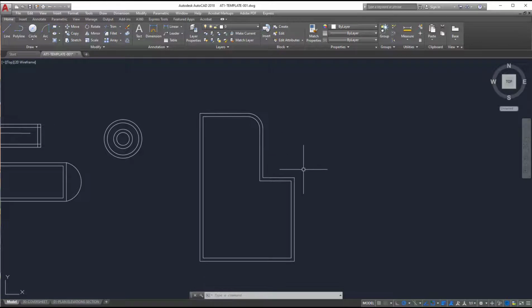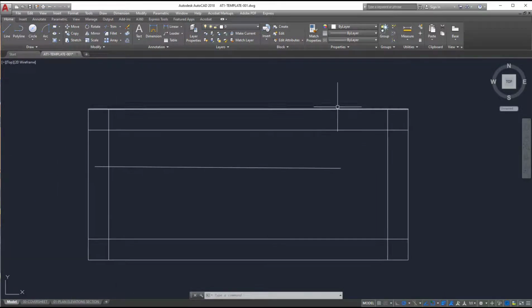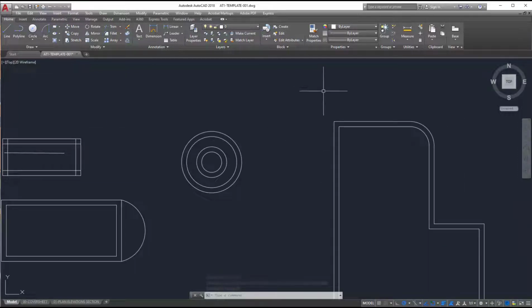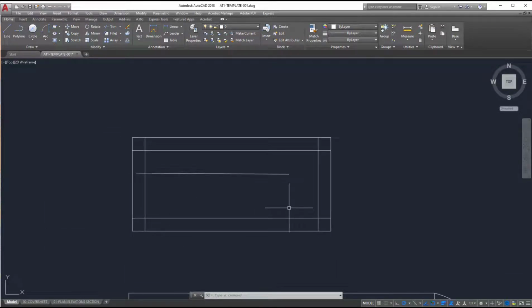The next one is trim. So trim is a great tool. And let's go back to this rectangle to use the trim command. So we have these outside walls, and we have these inside lines that we offset from the outside, but they're showing like this, which is not correct. We want to show our walls like this, where we don't have any intersecting lines here. We just see one continuous thick wall. So what we'll do is we'll type in TR on the keyboard, hit spacebar.